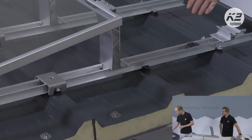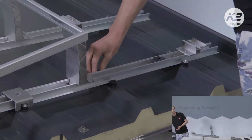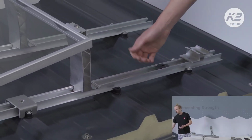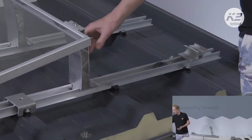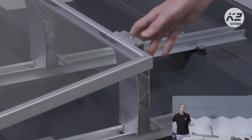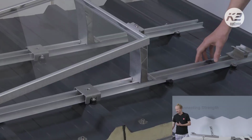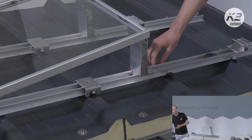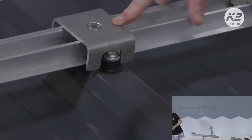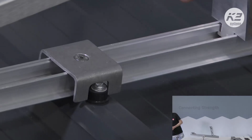If you know the K2 range, the basic rail is our standard basic rail solution fixed with our basic clips. This is the same product we use for our flat roof system and our D-dome. So we can use the rail and the pegs that we use for the clamps exactly how we do it for the standard flat roof solution, but on trapezoidal sheeting. Some of the advantages of this: there's obviously going to be no ballast. All of the forces are fixed, and this one has no screws. So maybe we just show this one here. The speed, the basic clip and the basic lock on as well.